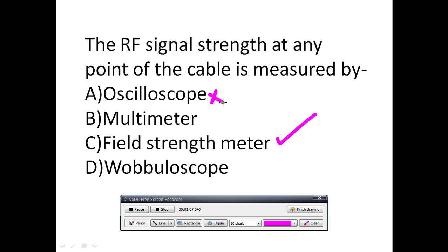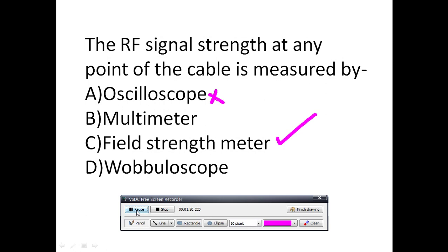Next question, very very important for RRB JE mains. Technical question. This is from the digital electronics subject. You might have studied it in BTech or diploma classes. The question is: the number of unused states in an n-bit Johnson counter is. Options are 2 power n minus n, 2n, 2 power n minus 1, 2 power n minus 2n. So, in order to understand this concept, we will go somewhat deeply as shown in the figure.